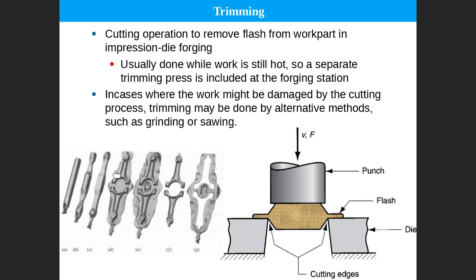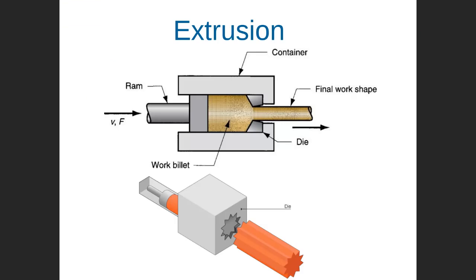Flash forging, as you can see here, you start and finally get the part here. This is the part, and this is the extra flash. It is unavoidable; it must be there. Then finally, you cannot use it in this way. You must take the part out and cut the extra material, which is the flash. Probably you can scrap it or simply recycle it. Then you need to do trimming. Trimming is to cut whatever extra material, then you get the part. So this is the trimming operation, and I think this is the end of the forging operation.